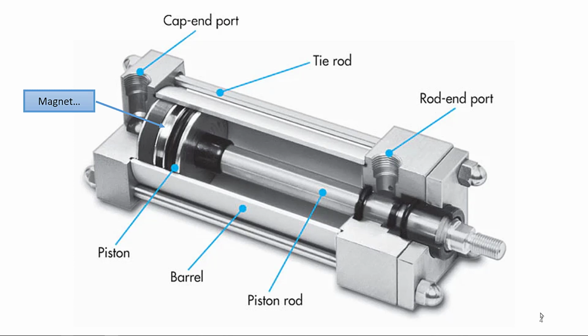But when you look at that piston, there's the cap end side, and we usually call that the piston side. And then there's the rod end side, which you can see. You can see the rod attached to it. Well, let's say that the piston end, the side you can't see, that's all the way up against the cap end, let's say that's 3 square inches, and you apply 50 psi of air pressure. That's 50 pounds per square inch. Well, with 3 square inches, that's 150 pounds of force when the rod extends forward.